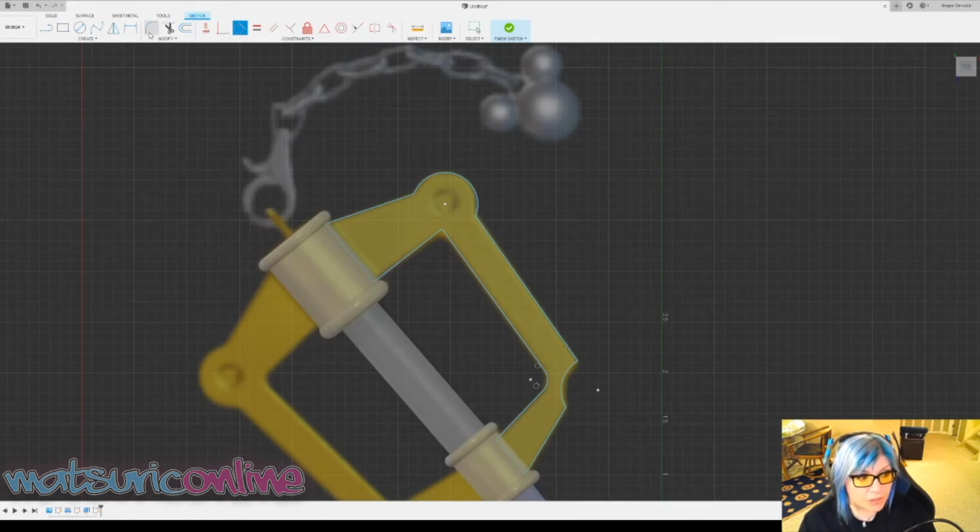So I'm going to go up to the toolbar, and in the modify bar, there's something called a fillet. Fillets are actually like radiuses, and you're putting rounded corners onto things. There's another function in here called chamfer. You can also use that, but fillet is probably the one that you're going to be using the most, mainly because rounded edges are more aesthetically pleasing. They don't hurt as many people. So generally you want to do some rounded edges.